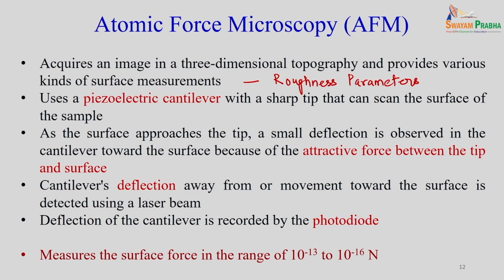And apart from the roughness parameter, it also measures the adhesion force. Now, how does it work? It uses a piezoelectric cantilever with a tip attached to it, which scans the surface. During the scanning of the surface, we can scan either in contact mode